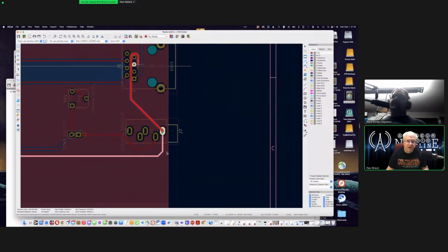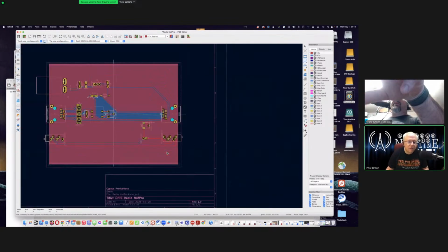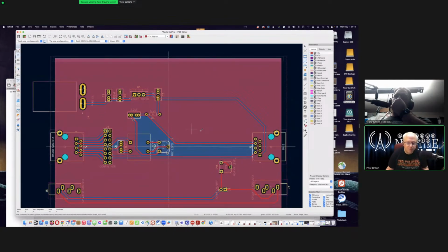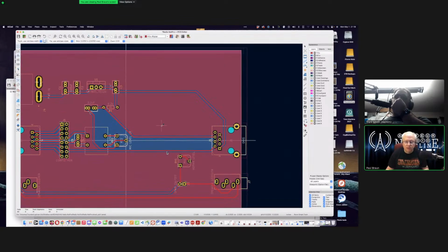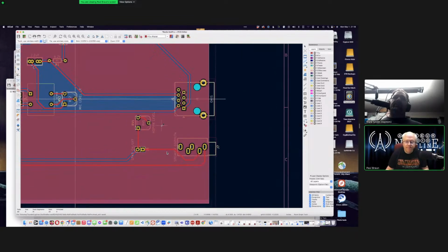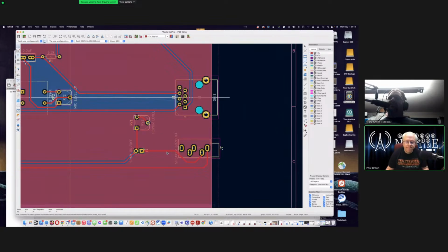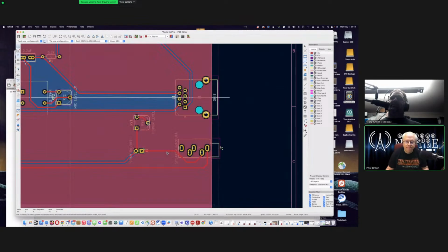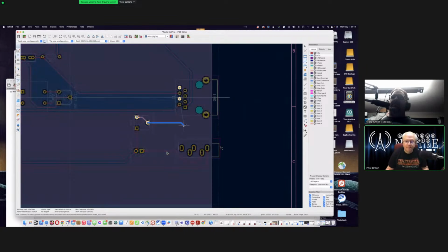All right. Yeah, that's going to have to be, or we do this. No, we'll go underneath. So I would go underneath. See what else. Go to the bottom layer. I think that's everything except those that have to drop down, and then we'll start punching in vias and throw in some artwork. Yeah, so let's get those bottom layer traces done. Let me show you how to do that. Okay, so this one is easy because you've got pads on both sides. So before you do that, select the blue layer. Yep, there you go.